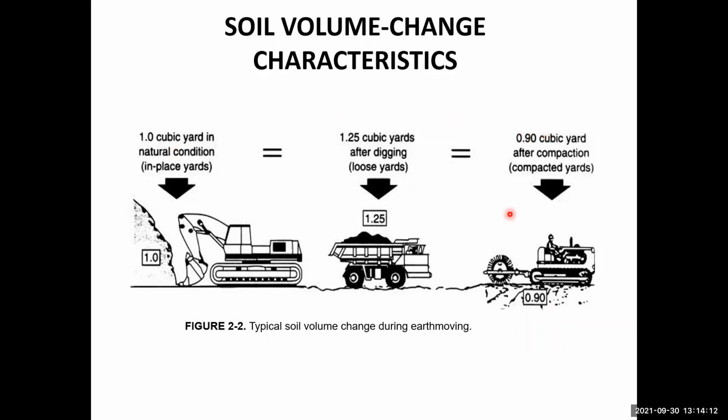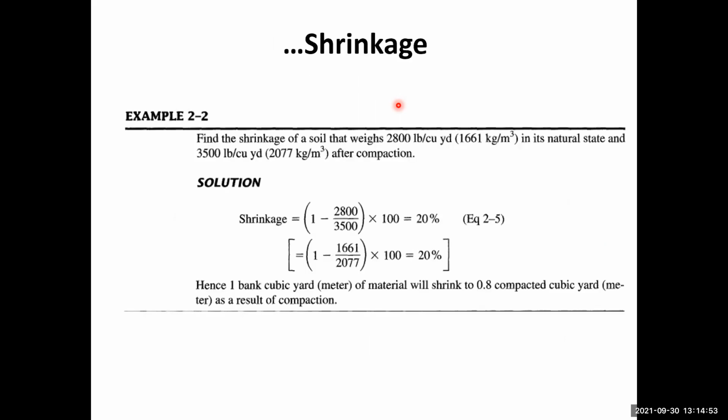So this is the concept and the places of application of these swell and shrinkage quantities. Swell is considered while loading and hauling the material. Shrinkage is considered when we are placing the soil in its final destination for filling purposes. This is how we put the swell and shrinkage in our calculations. So that was about the shrinkage.